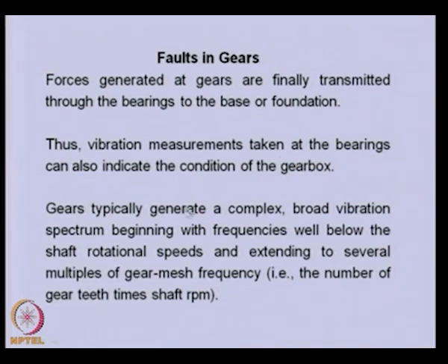Gears typically generate a complex broad vibration spectrum beginning with frequencies well below the shaft rotational speed and extending to several multiples of the gear mesh frequency. Gear mesh frequency is nothing but the number of gear teeth times the shaft speed.